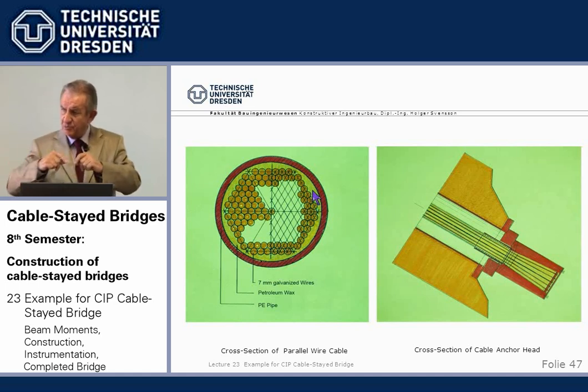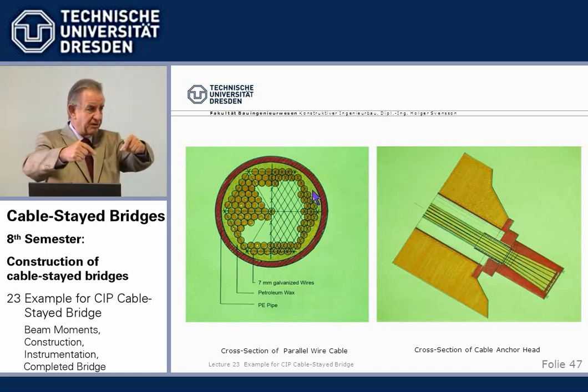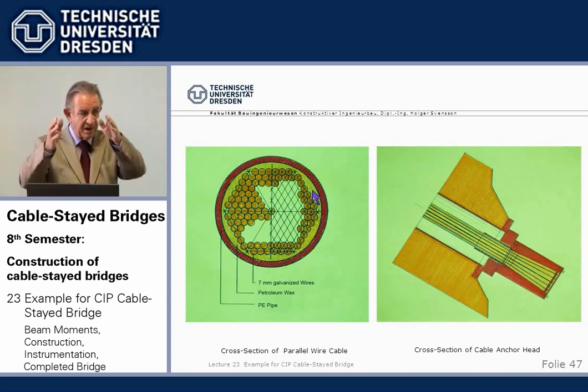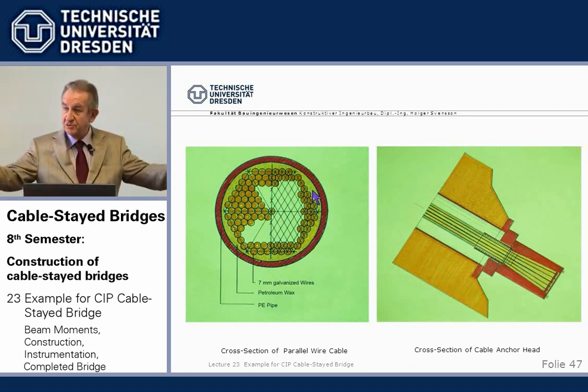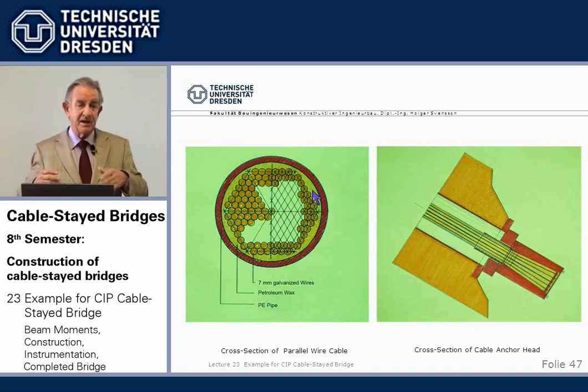But once it's installed and the sun is burning on it and the temperature goes down to minus 40, 50 degrees, it does not become fluid, because otherwise it would build up a hydrostatic pressure and we could get a big bulb and it could crack. So this is the trick. I like to say it has a consistency of chewing gum, something like that.